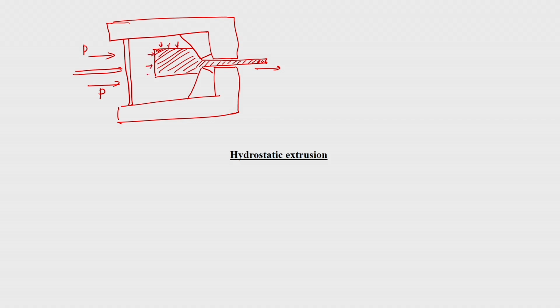And a fluid is filled inside this, and you pressurize the fluid by applying some force, maybe through a piston ram arrangement. So, this is a pressure cylinder, this is the die, and this is the fluid inside. So, from all directions you have a hydrostatic pressure applied. As per Pascal's law, the pressure applied in any fluid is equally transmitted in all directions. That is the advantage here.